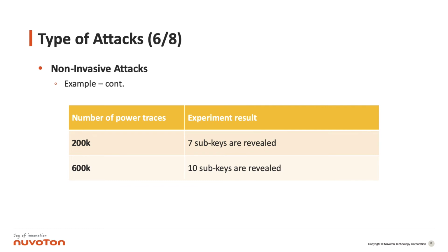This side-channel attack captures the physical characteristics generated when the MCU performs encryption or decryption, including timing, power consumption, or electromagnetic emission. Then it compares and analyzes them with the pre-established model to derive the encryption key.